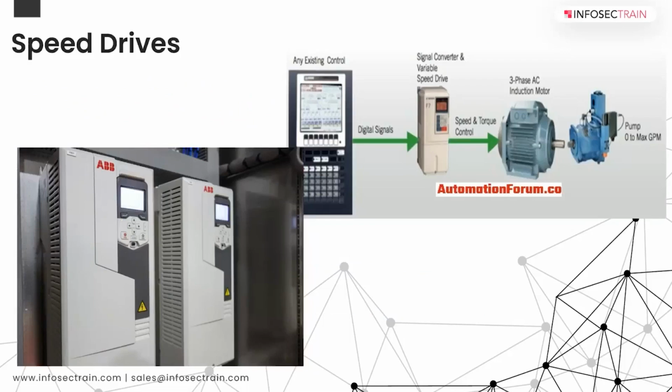So this hardware is called a speed drive. There's a variable speed drive. There is a variable frequency drive. They have the same concept, but how they work is different. So here's a simple schematic in terms of how the speed of the motor to control the pump operation is controlled by the variable speed drive, right?